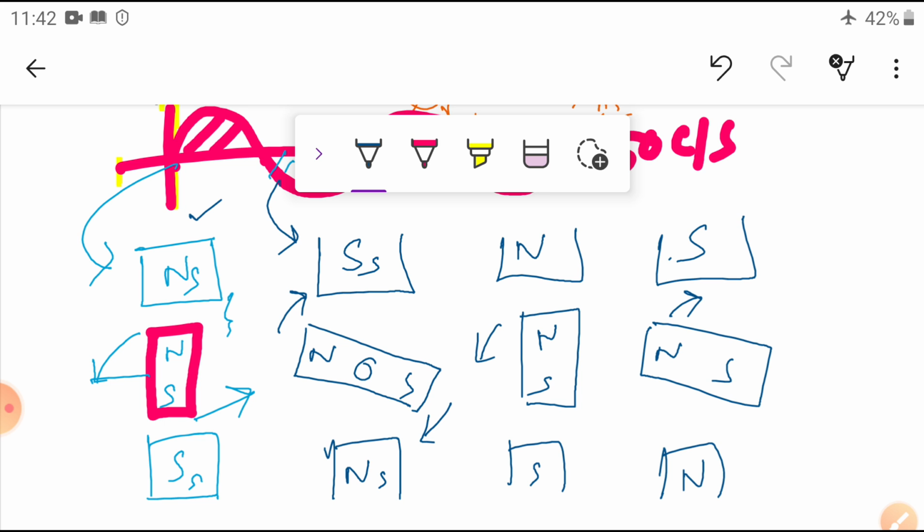One moment it is going anticlockwise, then clockwise, then anticlockwise, then clockwise, within fractions of a second, at 50 cycles per second. Due to the large inertia of the rotor, it is unable to follow this sequence, hence the rotor stays at standstill. That means there is no rotation of the rotor in the synchronous motor.